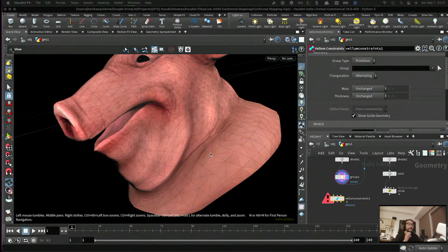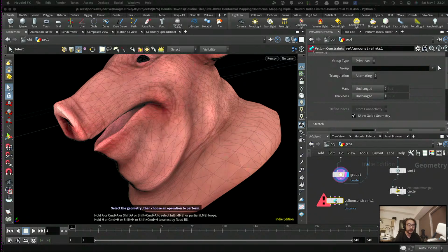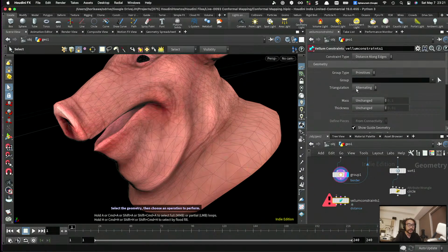So I want to keep the radius of each point to 0, meaning set the thickness of the physical property to 0. You can do that by changing the thickness somewhere on here, set up uniform to 0.